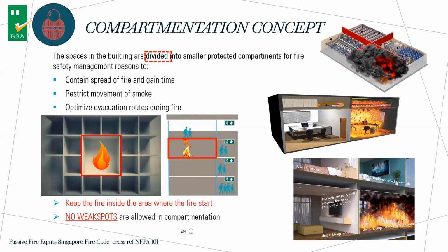Compartmentation also means dividing the usage. One side is office, one side is a storeroom. Because of the different risks, you want to compartment these two spaces. Compartmentation is also for separation between two units with different owners. So your party wall is also a compartment.